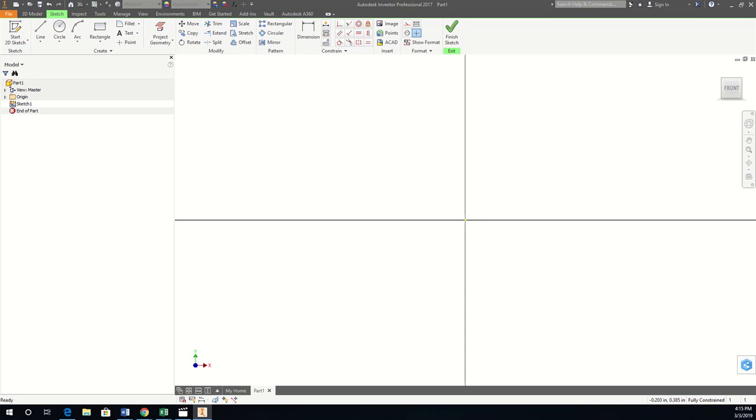Now, there are a couple of ways to do this. I really like the idea of putting your dimensions in as you go. It's critical that you always start at the origin. There are going to be exceptions, but in the beginning, let's be sure we've always started at the origin. I am going to choose line, and then I click here, here, and notice, okay, I'm going to Control Z that because when I moved my mouse to show you what to notice, it messed it up. So I'm going to click line again, click here.